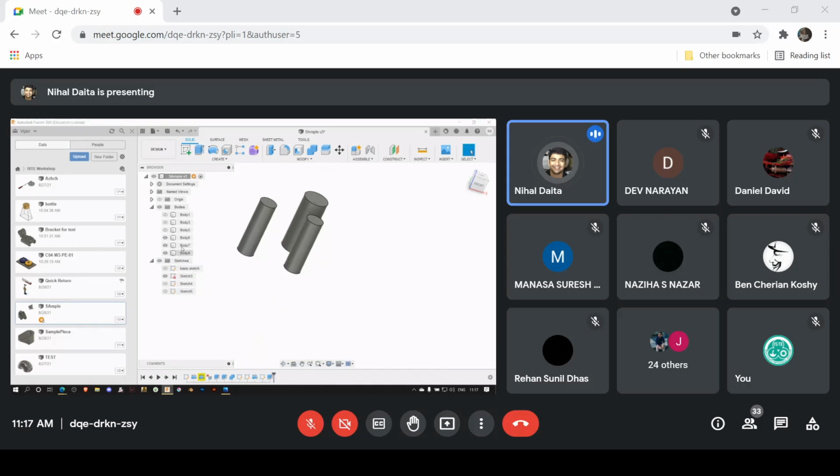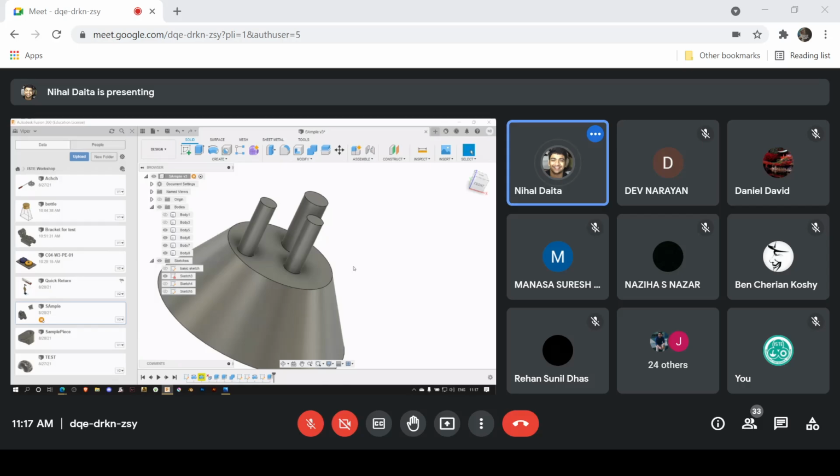I think it's lagged a bit. Okay, that's fine. Yeah. As you can see, these are the initial bodies. I just hid them for ease. So this basic body is body 5, right? Then body 6, body 7, body 8. So all of these are separate bodies, right? So there might come a time when you have to create it as separate bodies because there are a lot of parts in close contact and you don't want all of them to merge together. You just want specific ones to merge, right? So you split them at first. Then you just,